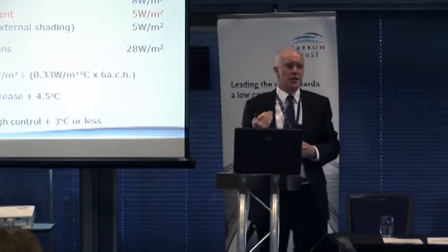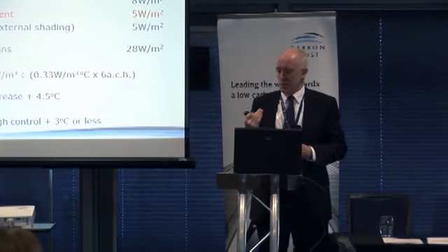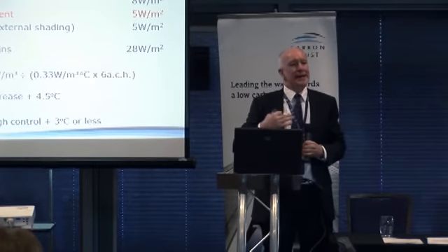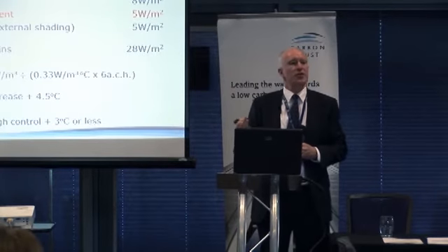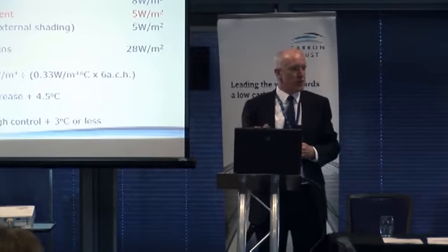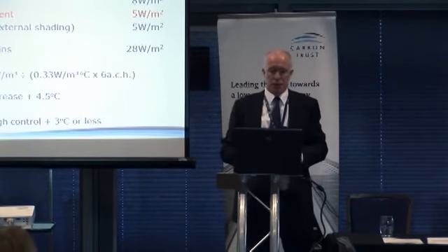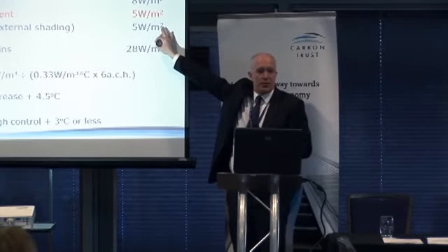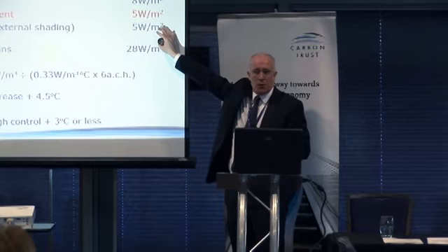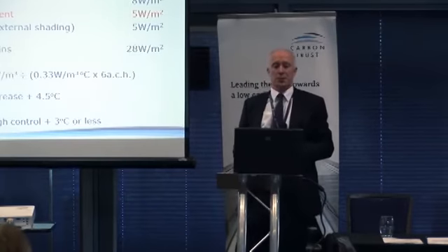The IT industry have embraced energy efficiency over the last 5 years. IT was not really embracing the carbon agenda over 5 years ago, I don't think. But if you approach your IT managers now, it's in their magazines. Low carbon IT technology is there. It's very much part of their industry now, and they're doing a great deal for the climate change issue. Typical office equipment is now down to 50 watts a person in a modern office environment. If you've got laptops or thin clients, you can get to less than that even, but that's the sort of level. So from 25 to 5 watts per meter squared.